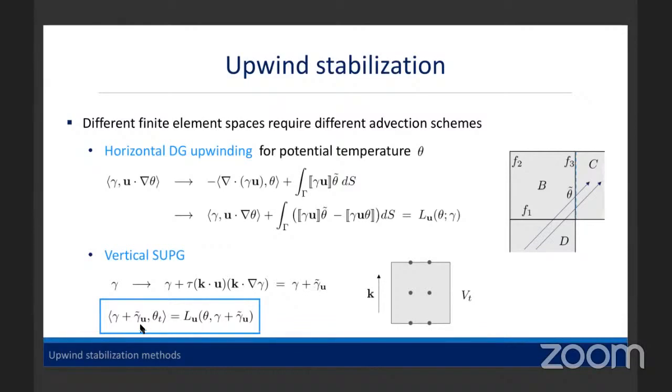And then I get this fully stabilized new temperature equation, which has a different advection operator and these modified test functions. And so I would like to have this, but I would also like to have energy conservation. So now I need to somehow combine these two concepts. I would like to have this thing in my Poisson bracket somehow and still make sure it's antisymmetric, because that's what I need for energy conservation.